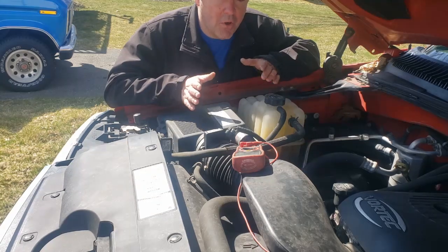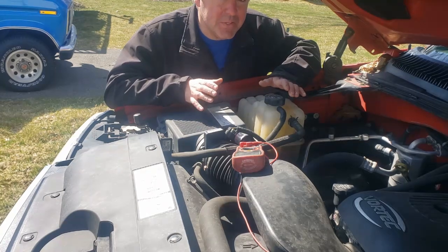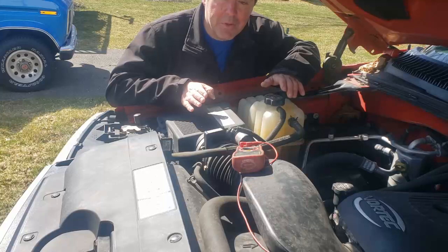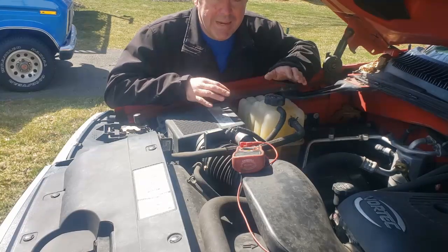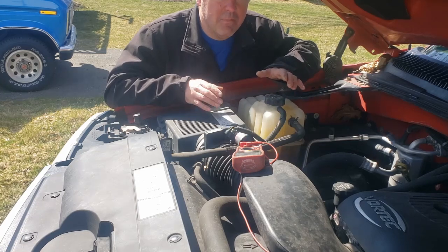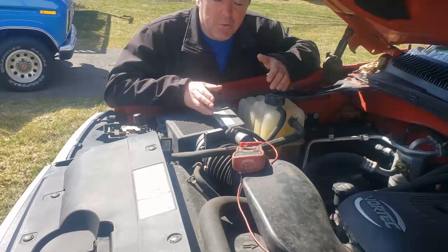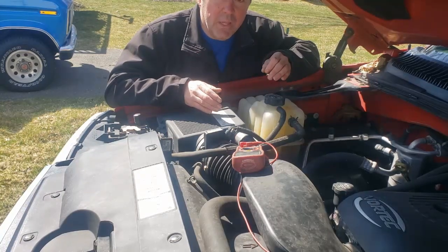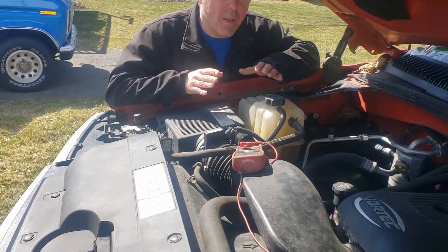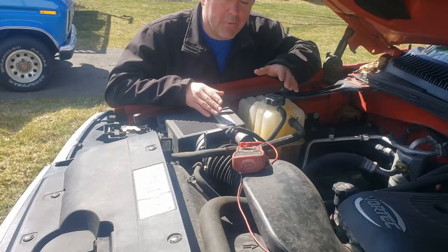Notice that my voltage started right around battery voltage, a little low to start with because I've been cranking this engine quite a bit doing these tests and have not restarted it. We do have to be careful doing these tests so we don't drain our battery down. It's a good idea once in a while to reconnect things and fire the engine up. But notice we started at about 11.8 volts, and we dropped down to 10 and change during the crank. That was voltage being lost between the battery and the starter motor. So those are two different ways that we can do that test. Both tests show that our cables, our connections from our starter motor to our battery, are good.